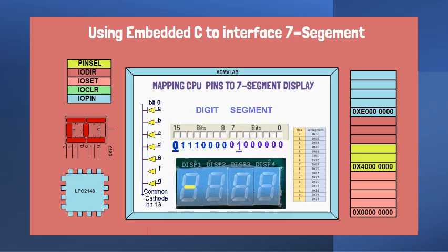The combination of the bits, or the truth table, is used by an embedded program to display hexadecimal numbers. We connect first 8 bits of an I/O port to segments A through F. While we connect bits 12 to 15 to the cathode of each digit. To select a digit for display, the embedded program grounds the common cathode bit of the respective display unit.